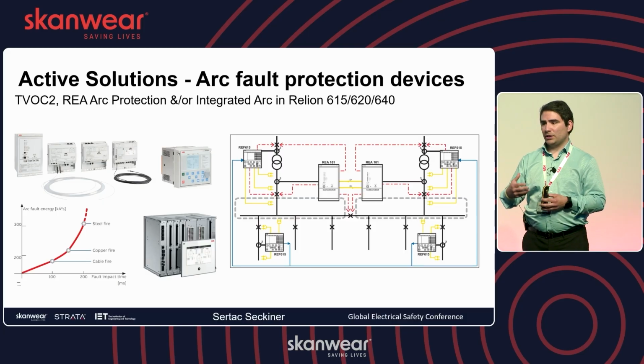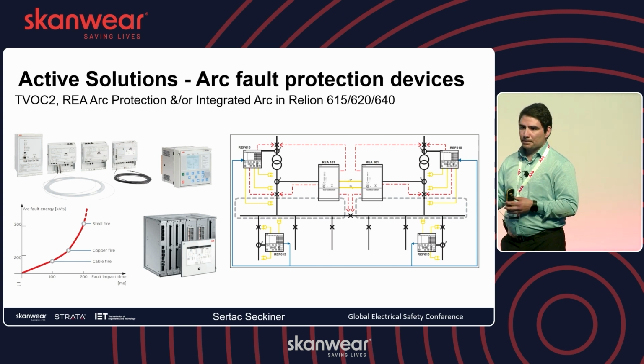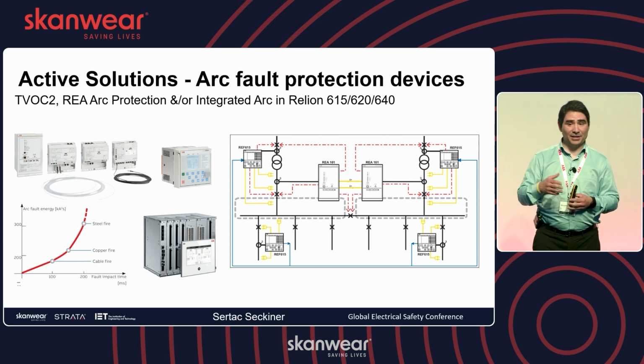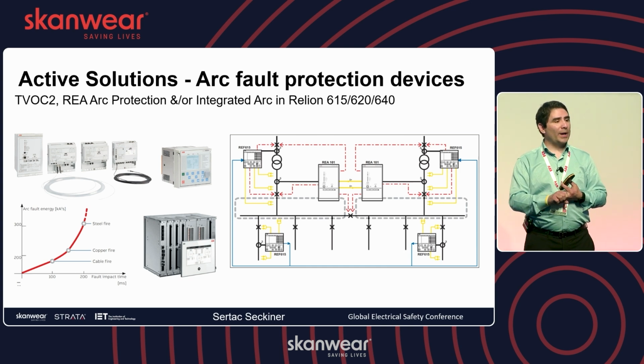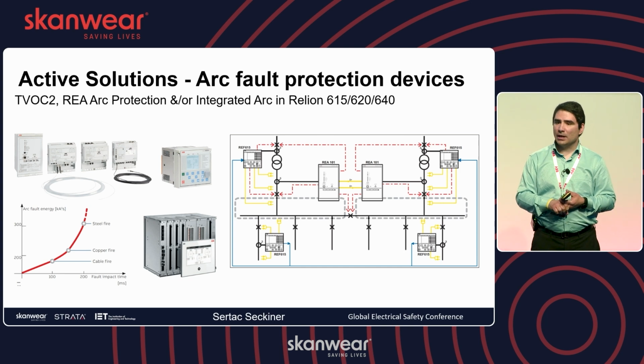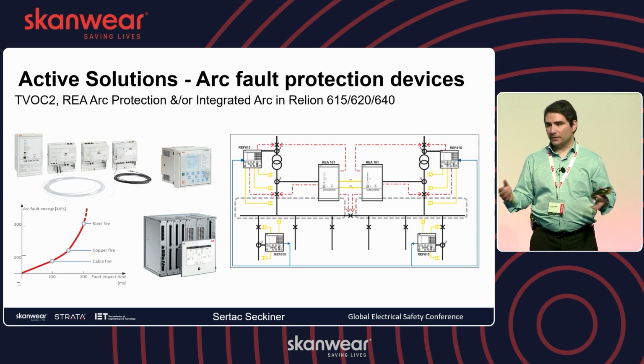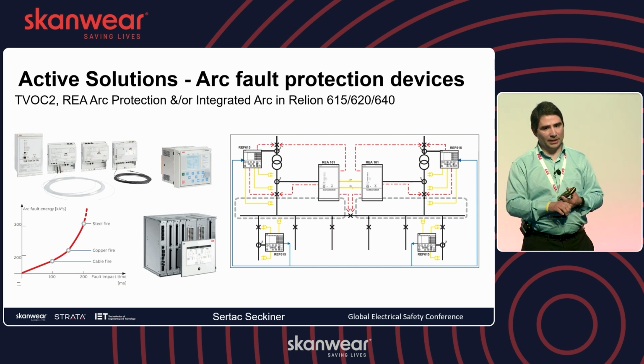And then lastly, the preventive actions. We can monitor our switchgear. Condition monitoring can be implemented. Thermal level monitoring can be implemented in the switchgear, which will tell us the status of the switchgear instantaneously, which means you can continuously monitor your system and understand whether it is aging, whether it will require any actions in due course, or whether it is susceptible to any potential arc flash or any other kind of fault due to the aging system.